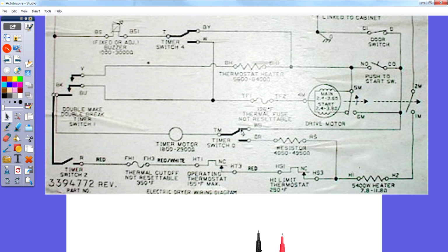This one's after the timer, but that's because it does something different with the timer, makes the timer work differently. But all these controls are on the line 1 side. We do put something on the line 2 side because line 1 and line 2 are basically the same in electrical voltage. They're just different phases, and I really don't want to get into that too much, but different phases, when they're put together, they add the voltage up. Okay? So by putting a switch on this side, we prevent line 2 from coming to the heater as well.